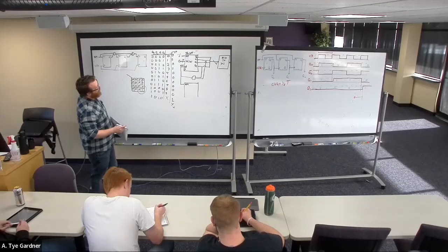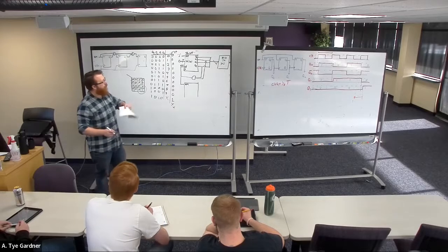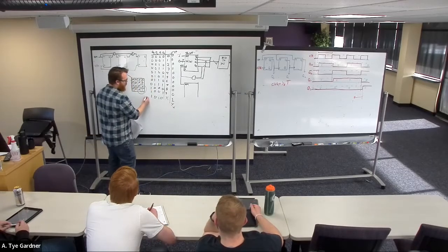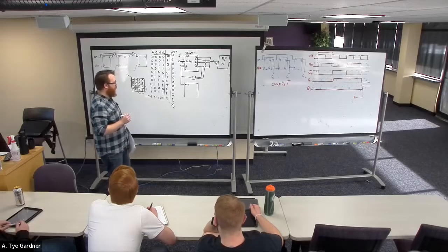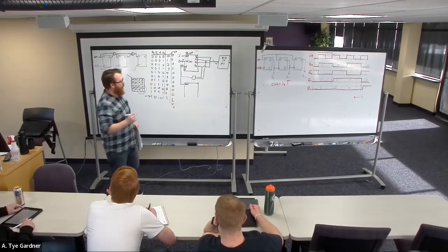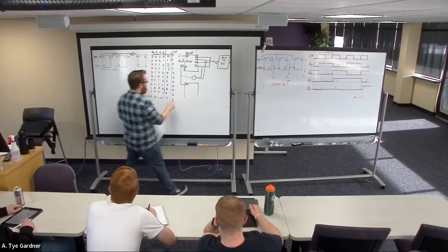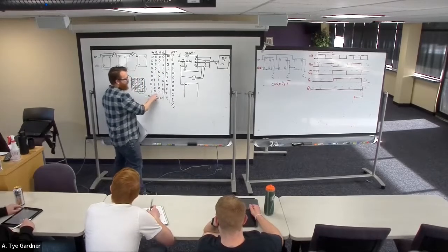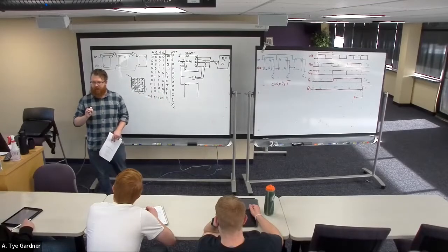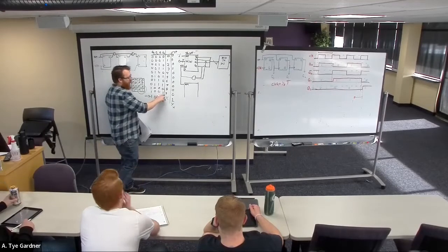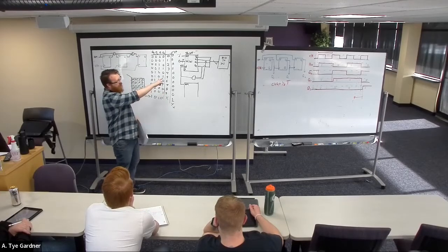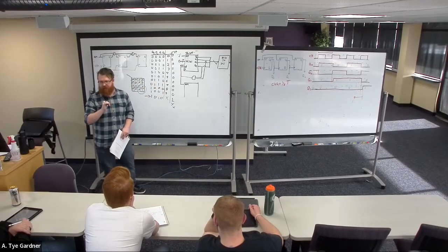I may have designed something wrong. We may have to do the timing on this because I was thinking about the reset timing in one specific way of designing it, the way that I would design it in VHDL. But I think the way that this is going to make more sense is because the reset is going to be coded, if we design it as a synchronous reset, that means that it won't reset until the next rising edge of the clock. So this is the design for an asynchronous reset or an asynchronous load.